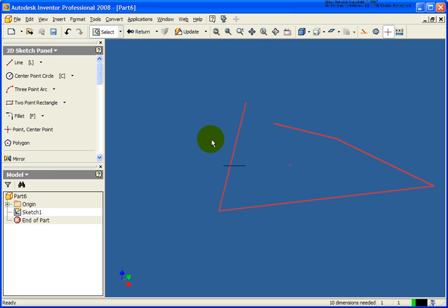So also while you're working, you may go back and place in another feature, and other operations may fail. And if that is the case, you'll notice in the upper right-hand corner we have this cross. Right now it's gray, and that's a very good thing. When that turns red, that tells us that we have a problem. When it turns red, go ahead and click on that, and that design doctor that we looked at before will walk us through how to fix that operation.